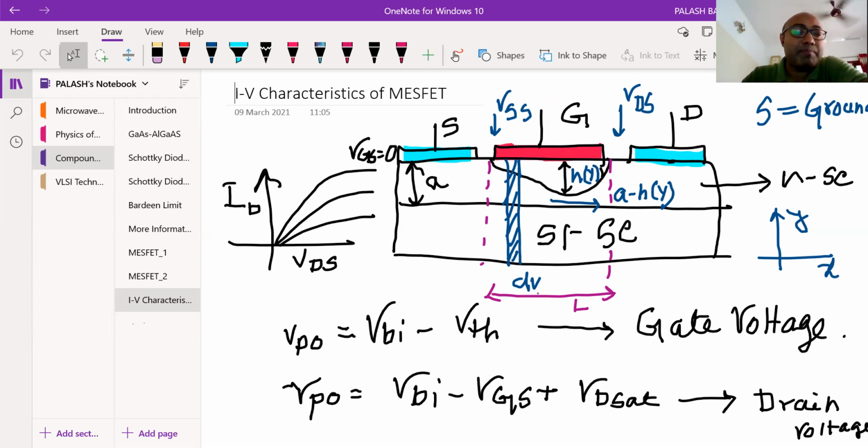Defects, okay, the interface layer between two junctions. Here for MOSFET, it is silicon dioxide, and across this interface my electron is flowing. So that is prone to defects, and electrons definitely get captured over there. The electron suffers a lot of scattering and everything, and mobility is reduced. But here you see the electron is flowing through the bulk, just like a BJT part. Here the electron is flowing through the bulk.